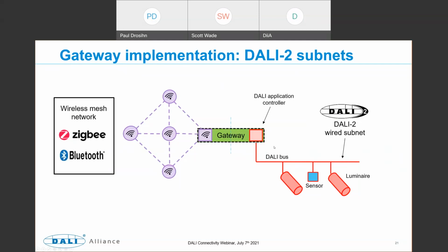So this is just an existing DALI network, and the gateway enables control of these DALI devices from the ecosystem. So any device in the ecosystem is able to decide to set the DALI lighting level to a particular output, maybe 50%, 60%. It can also start fades. Also, some information is available, and we'll have a look at that later.